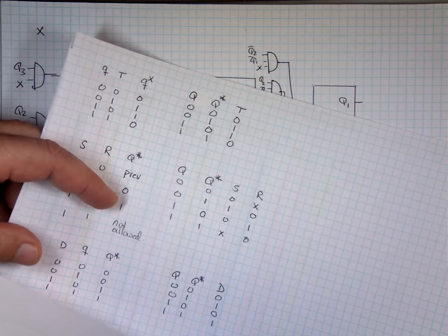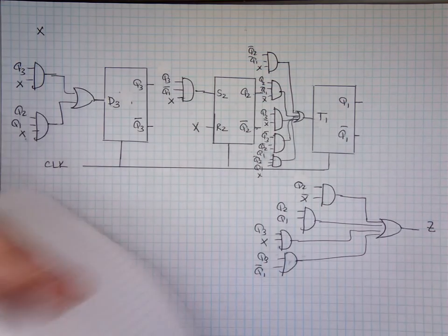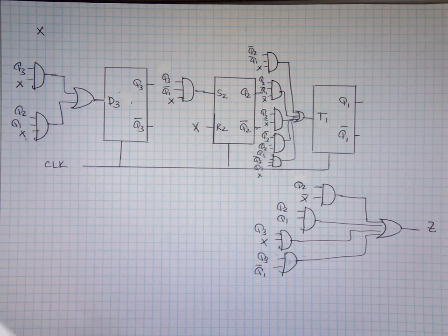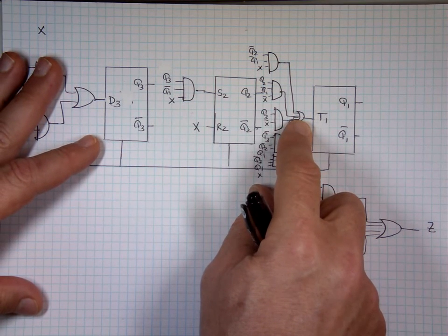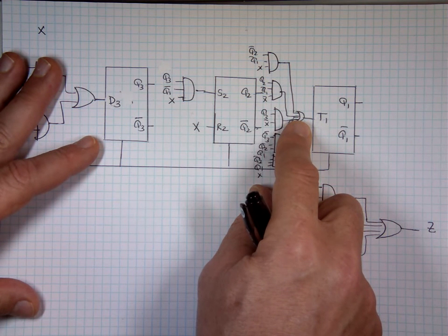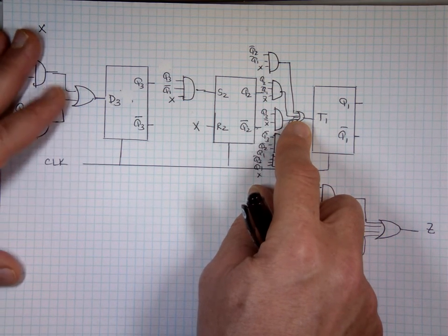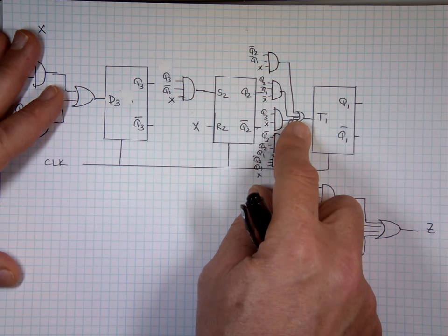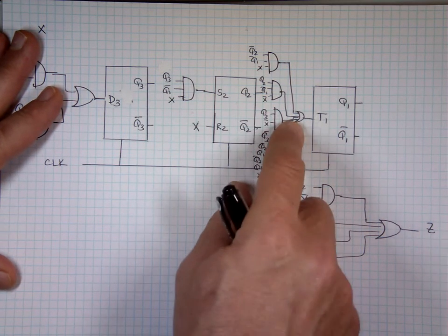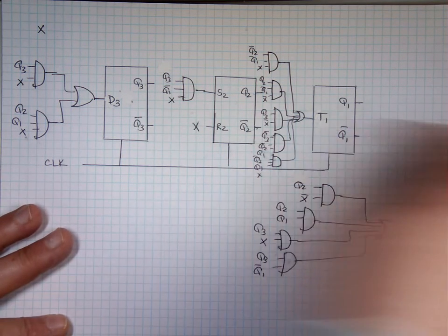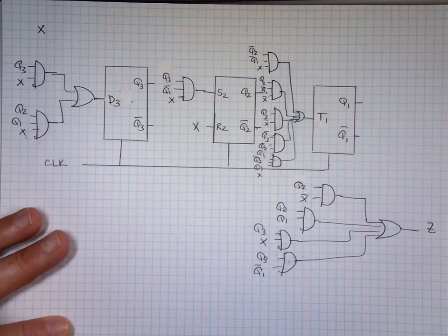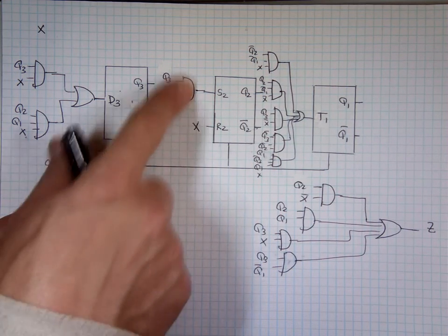Now what I could have done differently, I could have made my life easy. How? I said for this one, use a mux to drive it. I can guarantee you that. I put that last year on the final exam. To cover all the topics, I said use a mux to drive T1. 8x1 mux. What do you attach to it? So you have to go back and say, never mind, now do the K-map here. Let me figure an 8x1 mux. Use a decoder, for example, and OR gates to drive maybe this one. I don't know. I'll mix and match. So that's what I did.